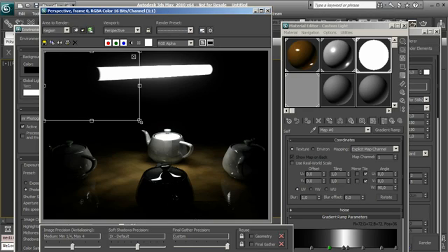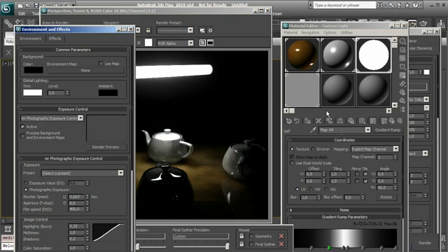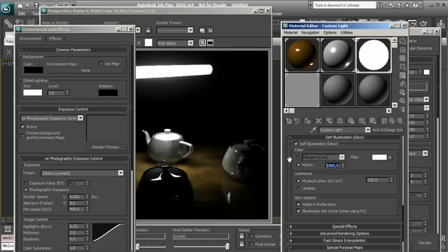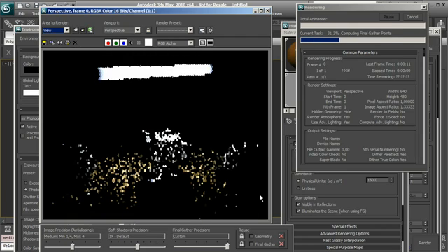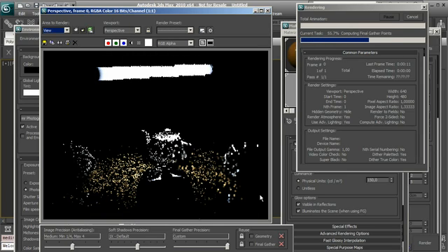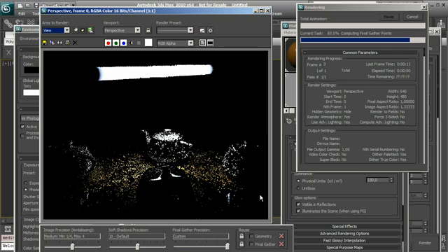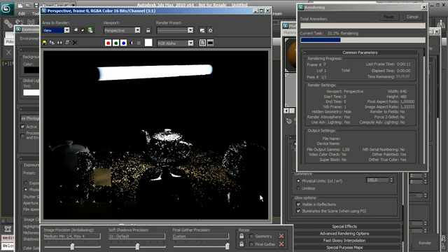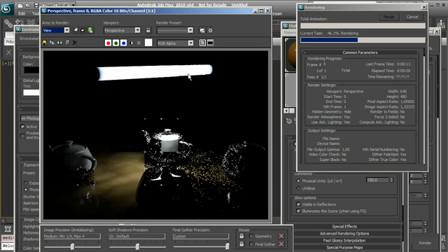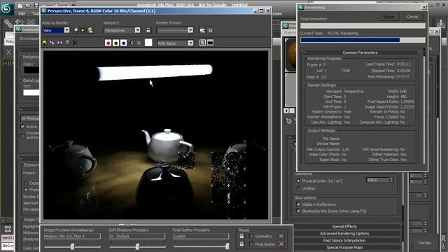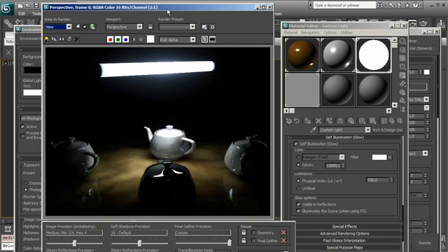Let's render also a preview, a complete preview, and let's use a different temperature, for example 15,000, and we are ready for the last rendering. And later, you know that you have just to change the final gather settings to obtain the final image. And you see that we have an interesting look there for the lamp. You can make it also more complex, but actually it can be okay for the preview.